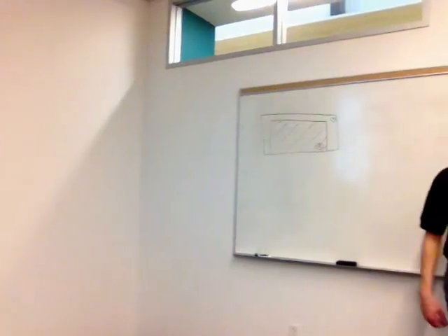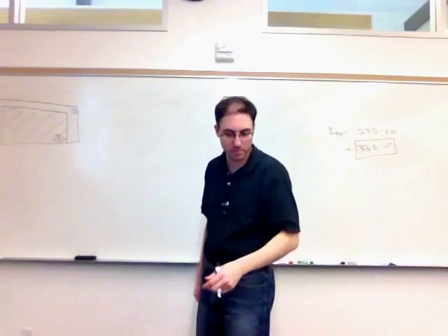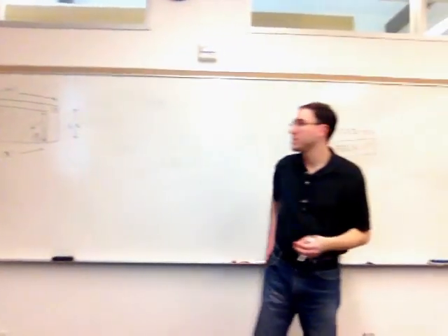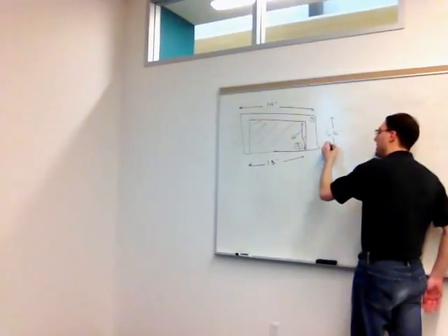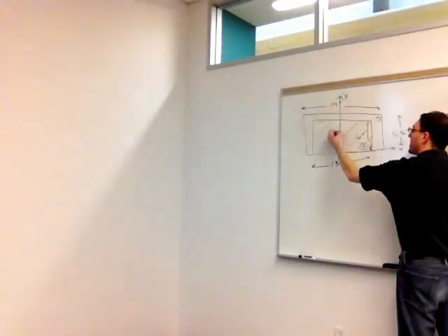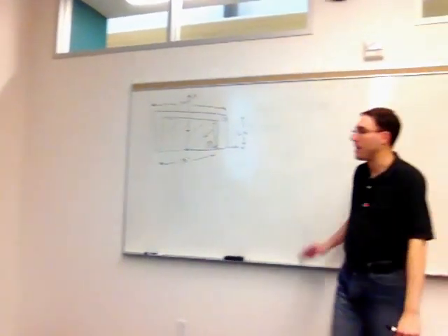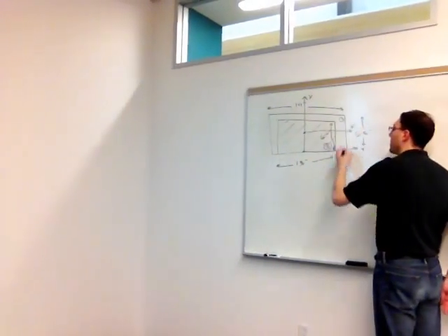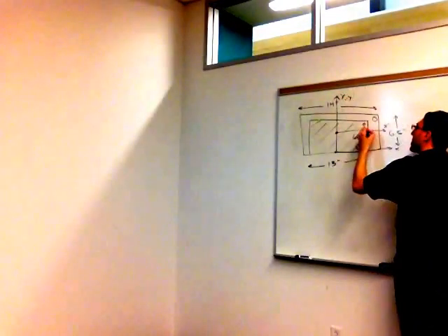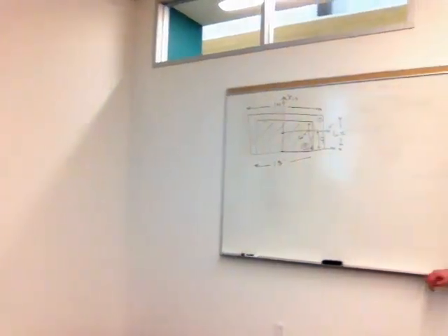I'll break it into two shapes, calling shape 1 the entire rectangle and shape 2 the cutout part. Stick with their given coordinate system, putting it in the middle and bottom of the shape. So the x-axis is down here. By symmetry, we do know the centroid will lie on the y-axis. We'll still go through those steps though. But the x-prime axis will be somewhere above the x-axis. And just like in the last one, it's going to be a distance of y bar above that x-axis.